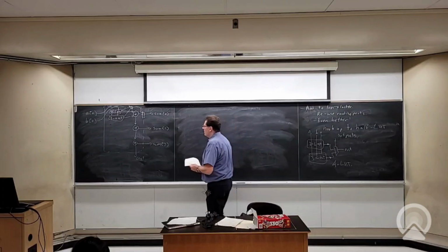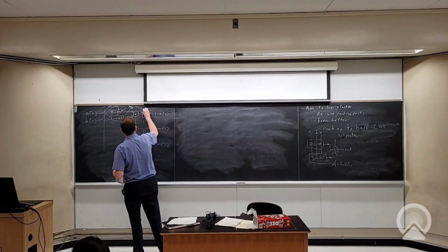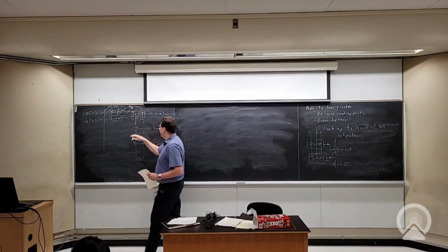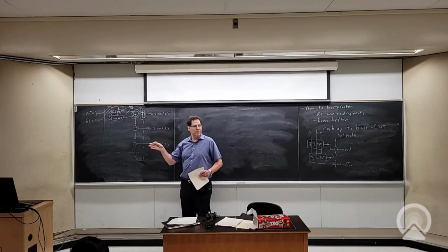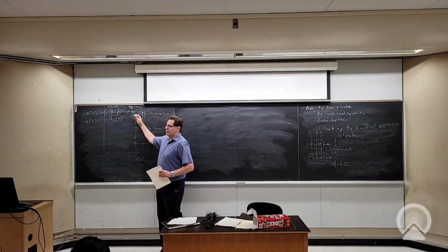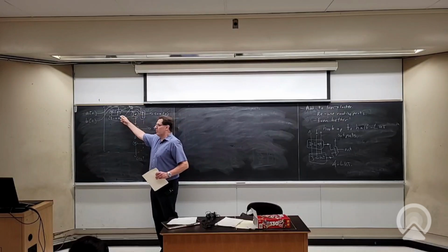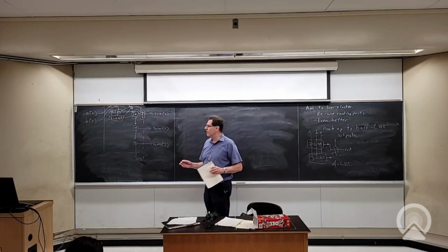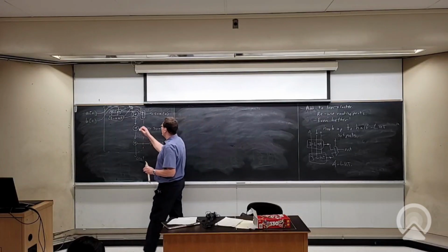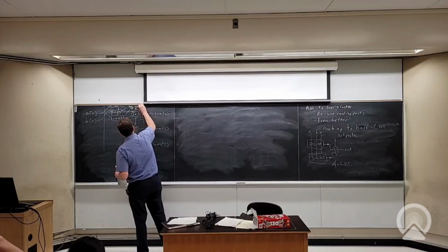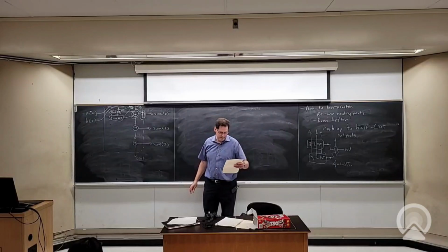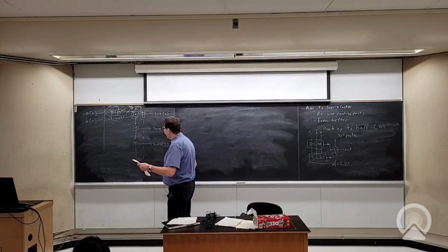Okay, and what I added is pretty minimal, right? I basically added this output mux, I added this adder, I added this piece of wire, after every LUT. That's pretty small, right? If I turn these into gates, they're pretty small compared to the LUT that I just put in, and they're quite small compared to the routing ports. And I didn't actually add any routing ports except a couple, a C in and a C out. So it didn't add much to the routing interfaces.